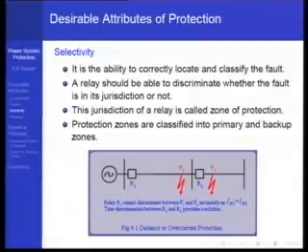The point is, people who argue against that kind of backup protection, against such a zone 3 backup, because of some problems which they foresee, because of the complications that they see in a developing voltage collapse scenario, maloperation of relay and so on, forget that if this zone 3 backup was not there, then there is no proper protection itself available.